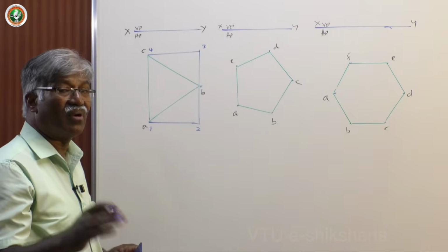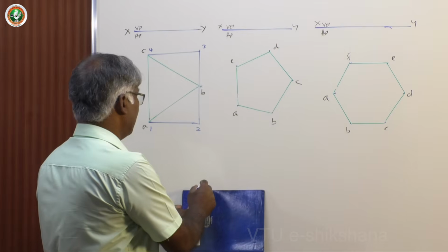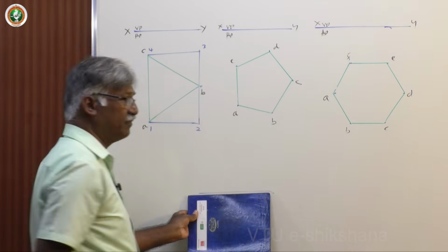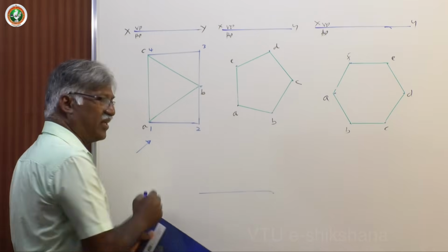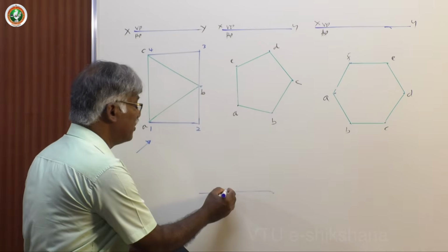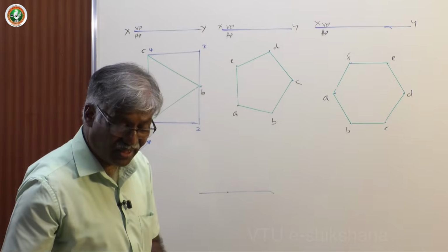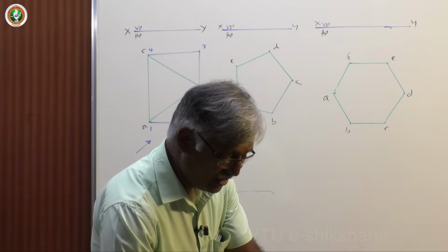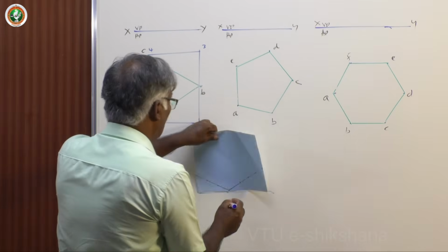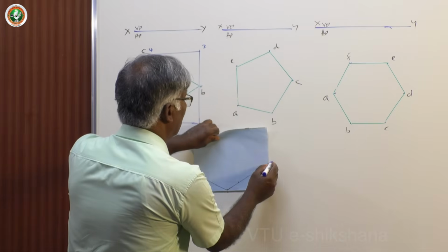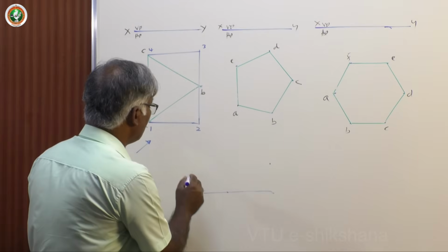I know how to draw the isometric projection of a rectangle. So start with a line, a thin line. Now I am looking from this direction. You can select the direction of vision. Now this is the point. Now take these 30-degree lines; particularly 30-degree lines you can prefer to draw manually. You can use set squares and do it.